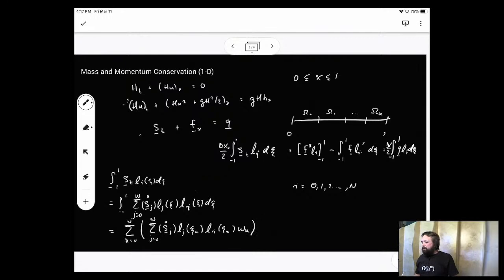If we make the judicious choice that the interpolation points are exactly the same as the quadrature points, we can take advantage of a Kronecker delta property of the interpolating polynomials. So I get delta jk here, I get delta ik here, and so the mass matrix, if you've done finite element analysis, this matrix that we're forming from doing this problem this way, is called the mass matrix.